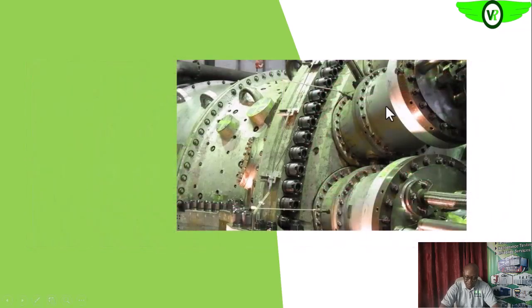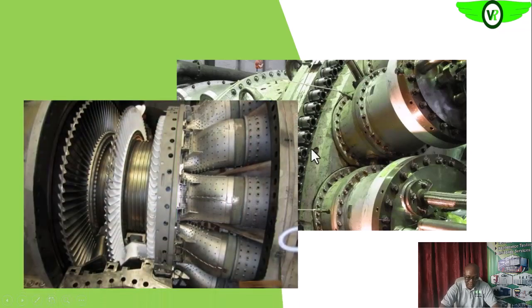So this is the combustor, a coupled one now, as you will see it physically. Then the combustion product, the fast moving high energy combustion product from the combustor, will now be sent through this transition piece. Are we getting it? Through this transition piece into the turbine section, as we will see later. So this is another very important component of the gas turbine.